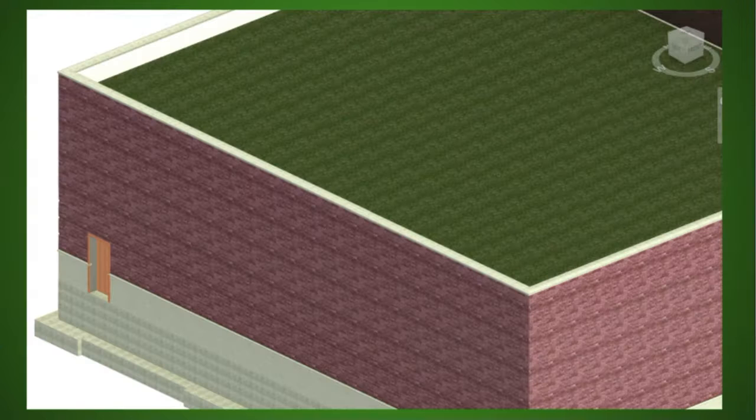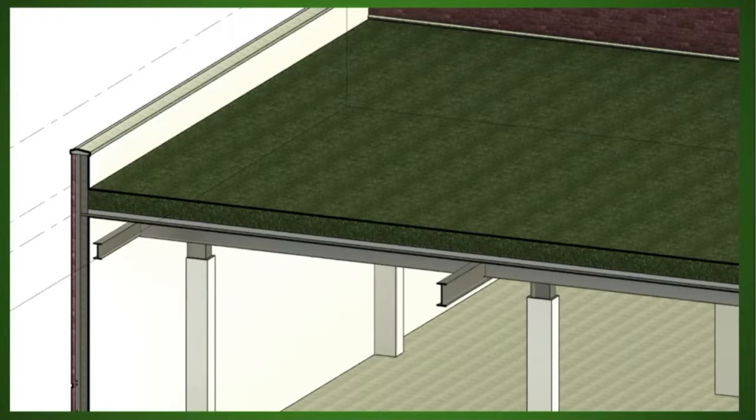For the library project, the ceiling of the first floor is going to be a roof deck, and that roof deck is going to be a green roof. And here I've just modeled a simple green roof. So here's a cross section of what that looks like. And the way it works is you actually have to define it as a floor to make it a roof. So it's actually the floor of the second story, but it's a roof for the first story.